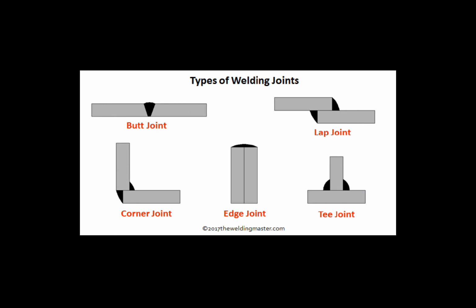What type of weld joints must be used to weld magnesium? Only butt welds. Prevent trapping of contaminants. What is one method of controlling expansion when welding a joint? Tack welding. At intervals along the joint.